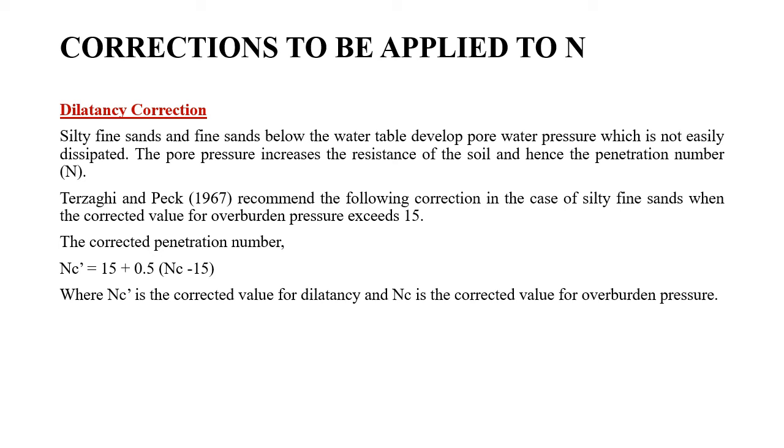Okay, and next, after applying the overburden pressure correction, if the corrected N value exceeds 15, then definitely you have to apply dilatancy correction. Okay, if it doesn't exceed 15, then no issue, we don't have to apply the dilatancy correction. And remember, this correction is applied only for silty fine sands and fine sands and not for clayey soils. Okay, because we find this dilatancy phenomenon only in such soils.